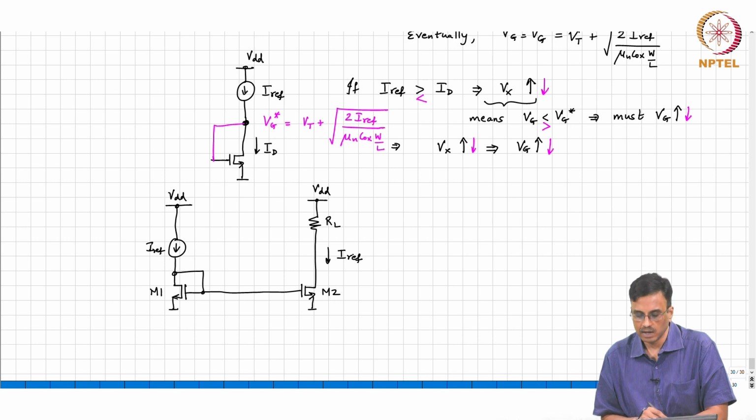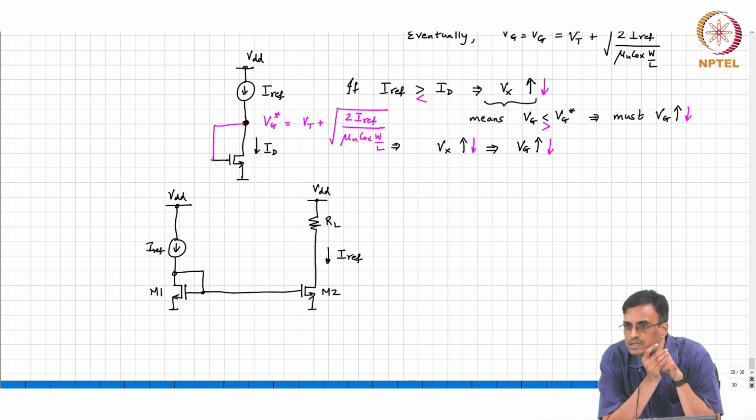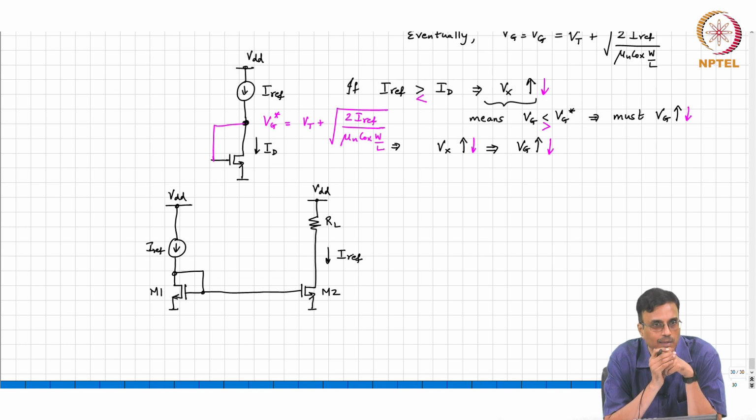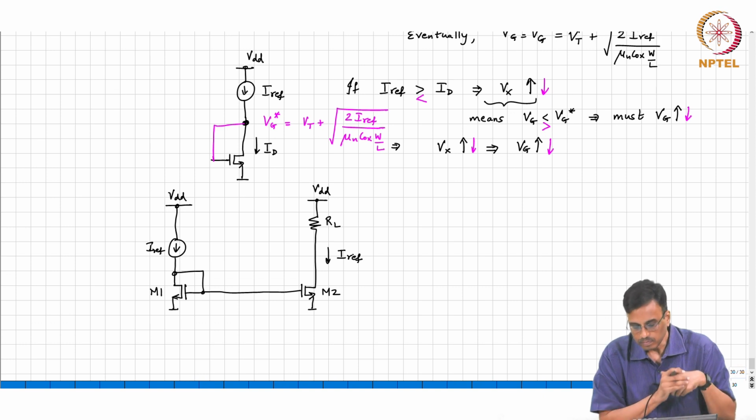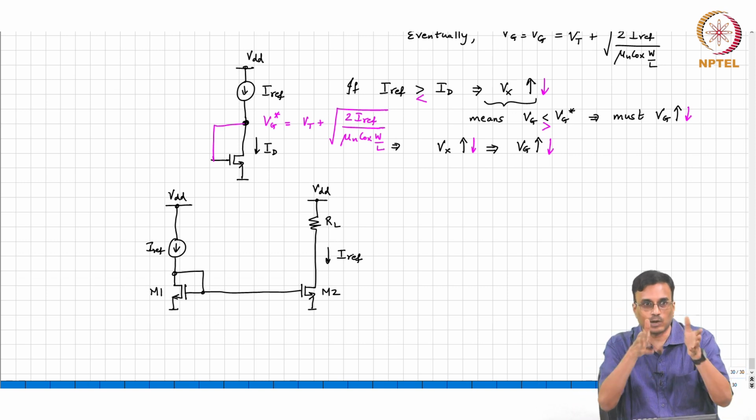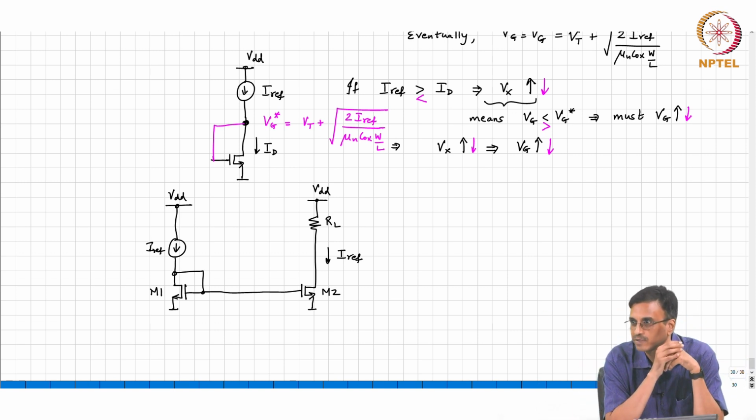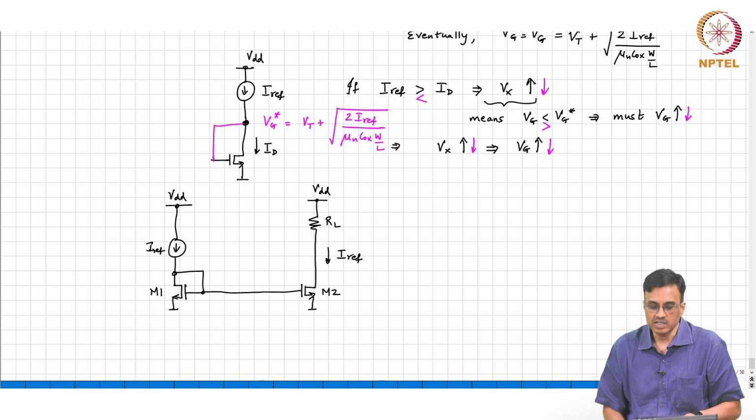And this current in the transistor M2 will be maintained at I ref irrespective of whether it's sunny or whether it's raining, okay, and regardless of what the threshold voltage of the transistors. Okay. So, this is an example of robustly biasing the transistor M2. Here it just so turns out that M1 and M2 are exact clones, they are not even approximately the same like all of us, okay, alright. And so this is one way of robustly biasing the transistor.